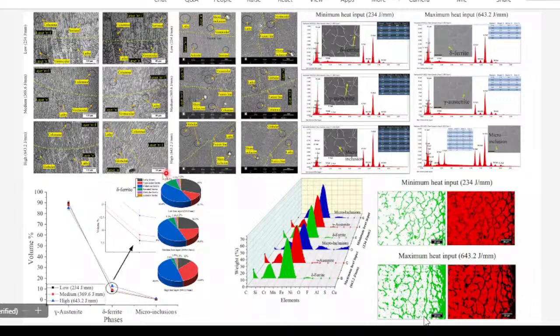You can see in the optical microscope images that in the transition zone, where the layer is changing, there is a major portion of globular ferrite, while in the interlayers we see vermicular ferrite and lathy ferrite.